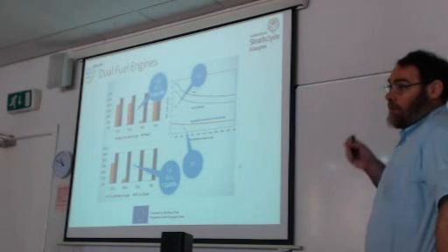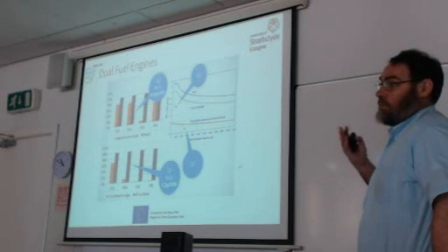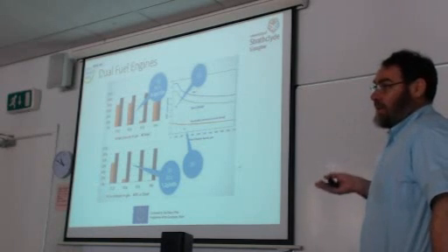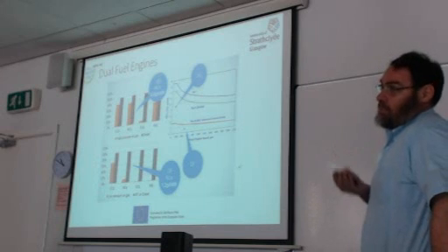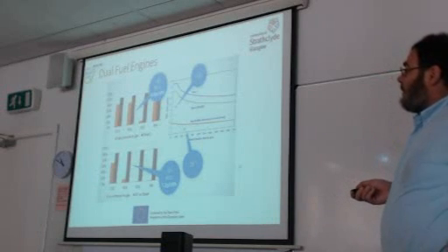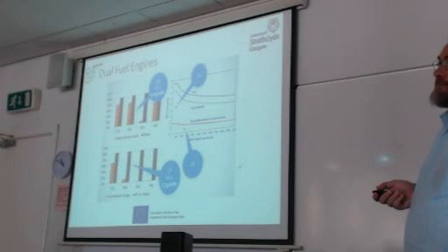Excuse me. Can I see the previous slide? Yes, of course. The upper one is based on the MAN B&W engines. Both are taken from Wärtsilä, because Wärtsilä has been producing gas diesel engines for 20 years. Apart from marine applications, power plant applications are extensive, so dual fuel engines and gas diesel engines have been extensively used in power plants. Are both based on four-stroke engines? Yes, four-stroke engines.